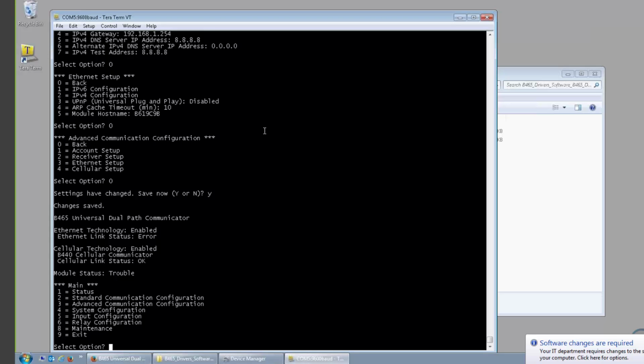Yes, that's not actually using those phone lines. That's where you would connect the phone line connector from the panel into there, and that's going to simulate a phone line. So it doesn't ever dial out on those at all. It just accepts a connection from the panel, makes the panel think that it has a real phone line. So it's not an actual communicator for monitoring if they have only phone lines in the building.